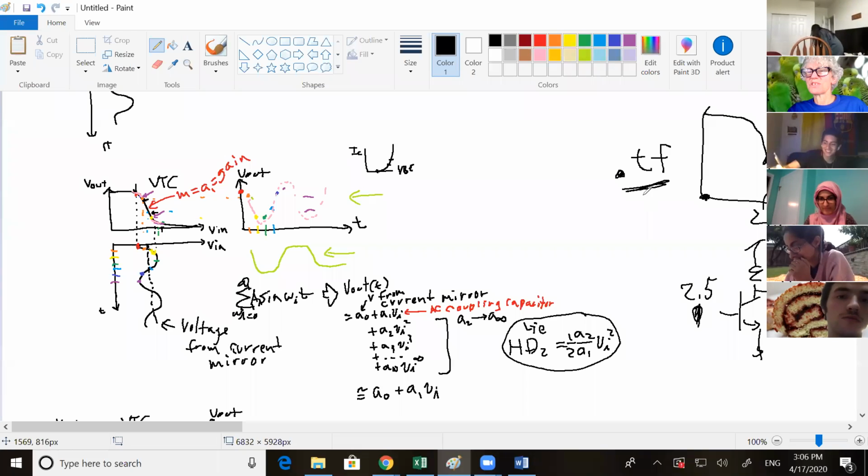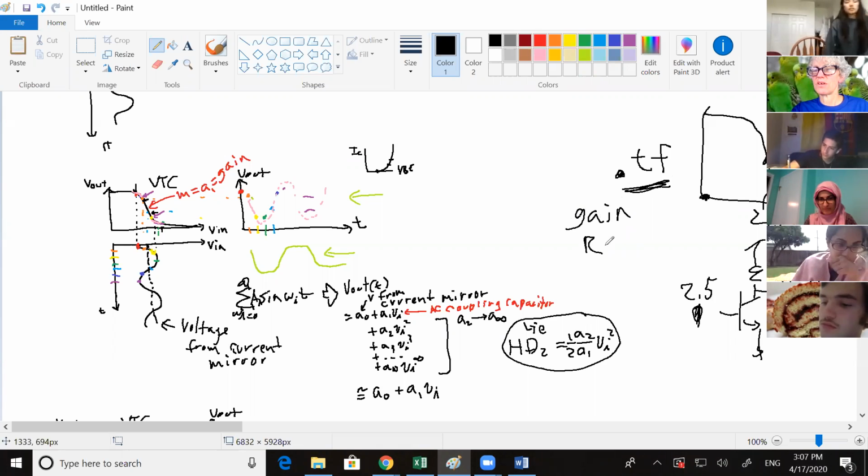You put 2.5 volts on there and you run a .tf. And you know how with a .op, you get currents and voltages, the display comes up in text? Yeah. This also comes up in text and it gives you your R in and your R out.